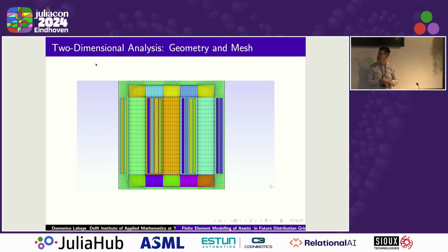What did you use to generate this mesh? Because this is also an adaptive mesh with quads. This is generated using Gmsh. Gmsh, okay. Nice. But then it's manually generated by the knowledge of the person. Exactly, yes, true. This is done because obviously these computations have been done before. We're not the first ones to do this, so you kind of expect issues to appear and take the precautions. That's true.